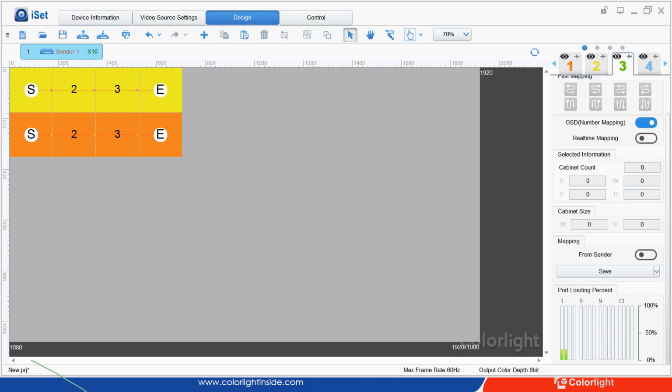So let's look back to the toolbar on the top of the software. Click the finger button to highlight your panel on the LED wall. You will be able to see a flashing box on the panel you highlighted. And if the panel has an indicator in the back, the indicator will be flashing differently from the others. It could be flashing fast or changing color. This feature significantly helps field engineers do on-site troubleshooting.